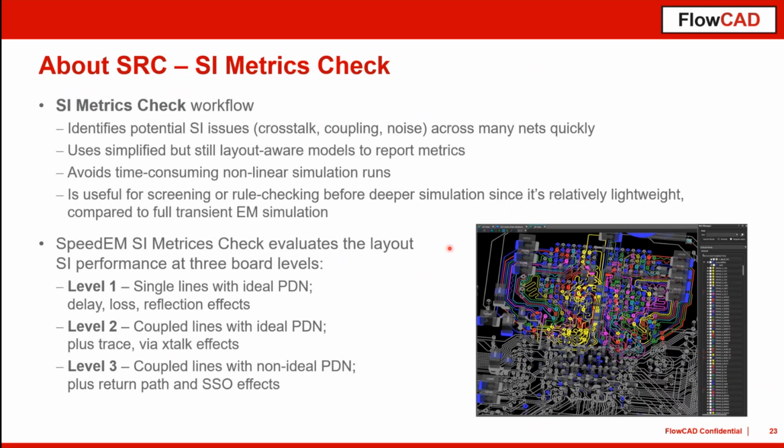At first, I want to start here with the SRC-SI matrices. SRC means that we have a simulation rule check, which is a little bit different from ERC, which means electrical rule check. The simulation rule check is intended to evaluate the key signal integrity parameters of high-speed channels, such as serial links or source synchronous buses. Here we do not have to extract the traces in the frequency domain. We do all this analysis in the time domain, which enables us to simulate very large groups of nets.